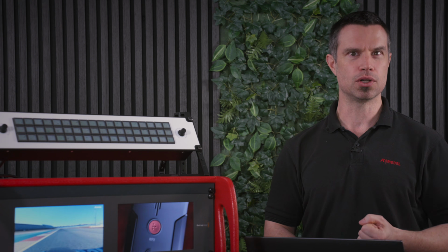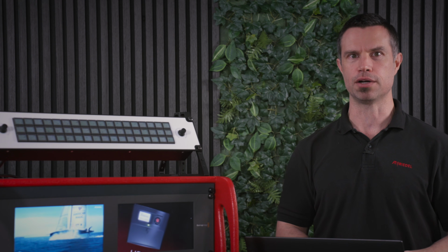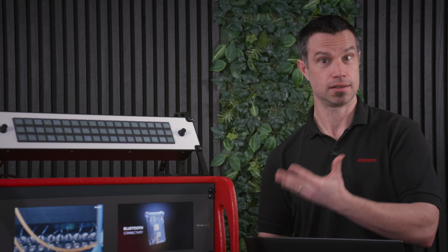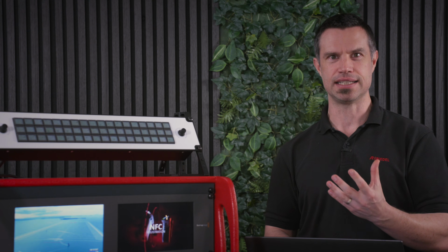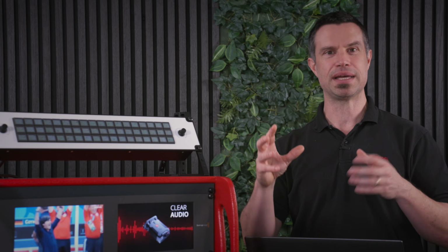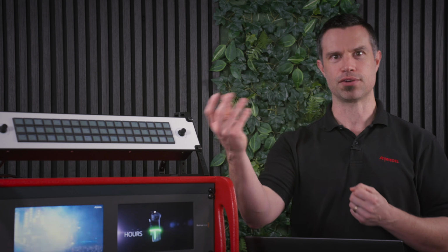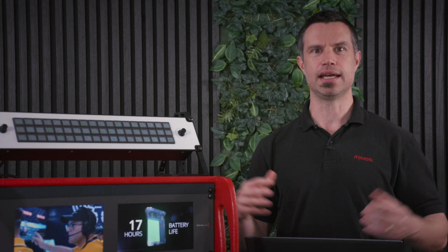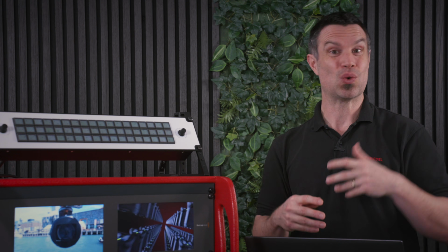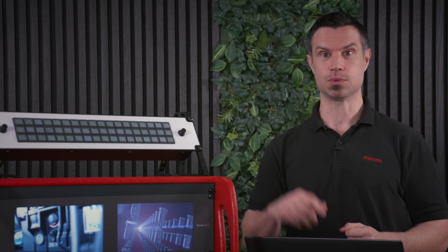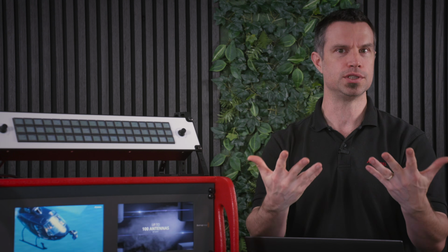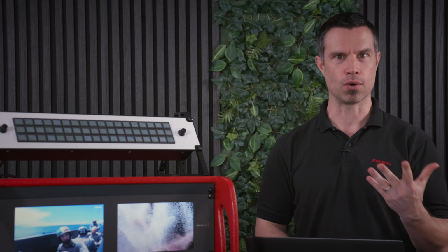So if you take the example of Simply Live, the live production suite by Riedel, you can have live signals coming in as SDI or 2110 eventually. And we can have NDI signals coming in as part of the graphics for the overlay. And these can be coming in different formats. The live signal is SDI, the graphics is NDI, for example. And then we need to blend those together inside Simply Live. Now, when we're routing the signals, we don't actually care what the signal format is. We just want to make sure the right graphics feed gets together with the right camera feed in order to produce the correct program output for the viewer at home.